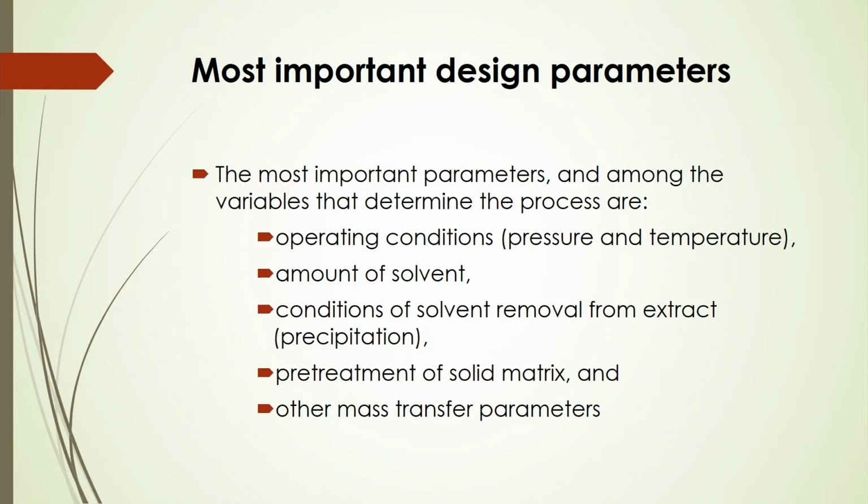Everything should be considered for the optimization of this design. The most important design parameters for this extraction process are the operating conditions, that is pressure and temperature, the amount of solvent, conditions of solvent removal from the extractant, and also the pretreatment of the solid matrix and other mass transfer parameters. So, these are to be considered as design parameters.